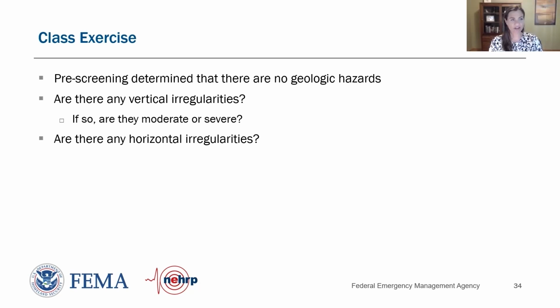Yeah, so that tower, the taller part, was sort of L-shaped in plan. So I would say that that's a horizontal irregularity for the re-entrant corner. With the re-entrant corner. Okay, so we've got vertical and horizontal now.